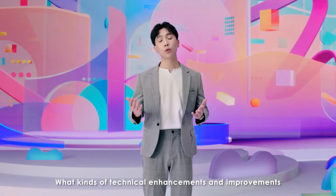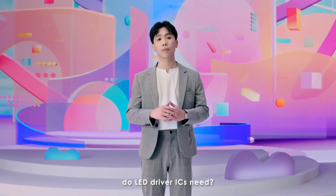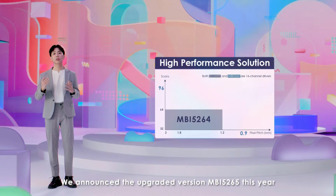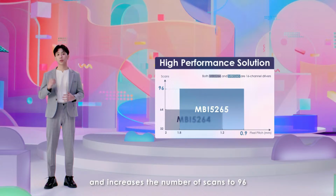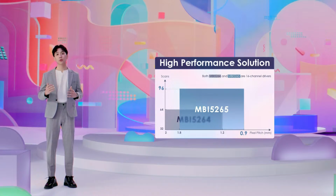What kinds of technical enhancements and improvements do LED driver ICs need? Macroblock announced the 16-channel MBI5264 high-performance solution last year. It's in production now. We announced the upgraded version MBI5265 this year. It features excellent display specifications and increases the number of scans to 96. The pixel pitch is reduced to P0.9 from P1.2.